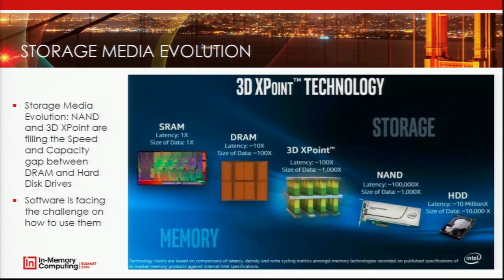Will this piece burn out? The answer is yes. If we put a very hot database inside NAND or 3D XPoint, and certain areas get hot access, like 30,000 times, that area will wear out and burn.